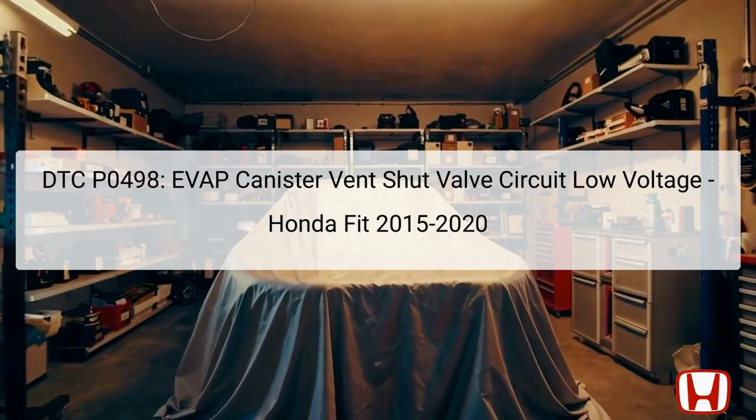The Diagnostic Trouble Code, DTC P0498, indicates a low voltage in the EVAP canister vent shut valve circuit. In vehicles like the Honda Fit from 2015 to 2020, the EVAP system is crucial for controlling emissions and ensuring that unburned fuel vapors are managed efficiently. The EVAP canister vent shut valve plays a vital role by either allowing or preventing the flow of vapors from the fuel tank to the charcoal canister.